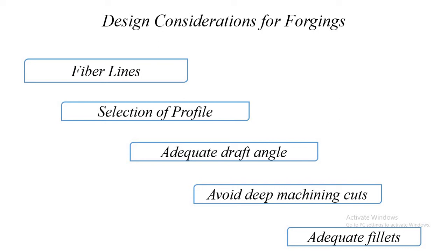It is advised to avoid deep machining cuts. The designer should avoid deep machining cuts because in forged component, the cut breaks the fiber lines and makes the component weak.